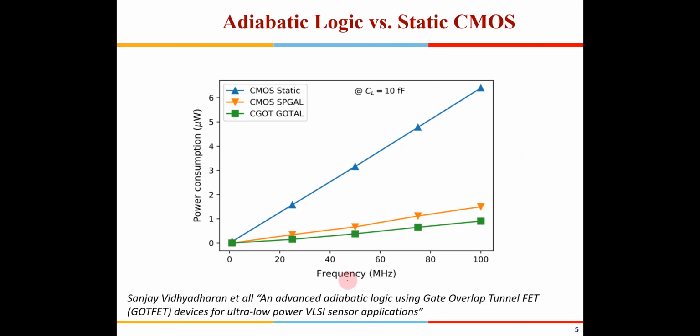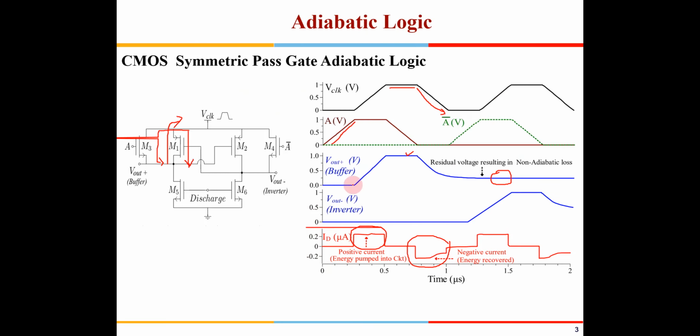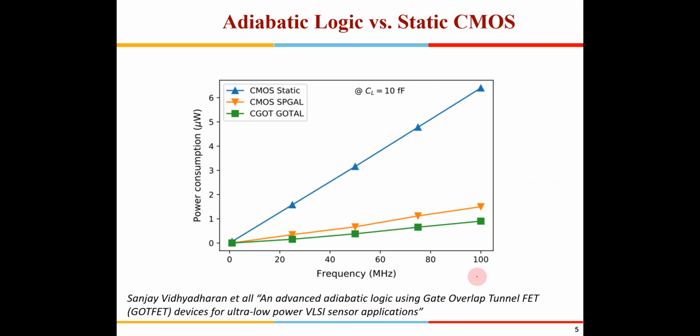Okay, now the only issue out here is you need to allow this VDD and the V out to follow each other as close as possible. So you can't have it two operating, yeah, it is like a power supply boost circuit. Yes, correct. The thing is, we need to allow clock and V out to follow each other as close as possible, and for that reason the adiabatic circuits generally work in the range of 100 megahertz, not more than that. So if you go for higher frequencies, then you will find that these adiabatic circuits won't work fine.